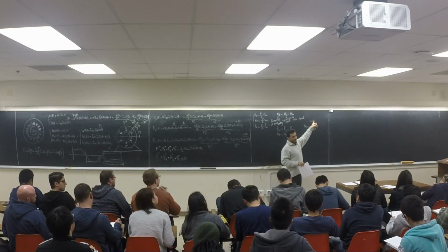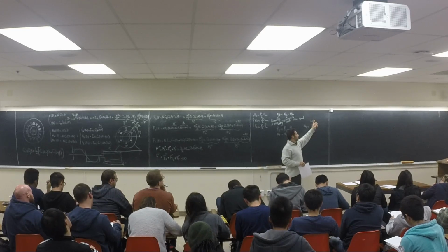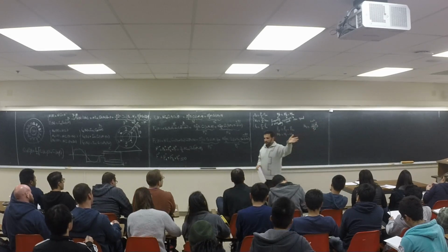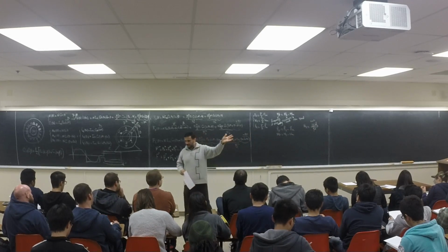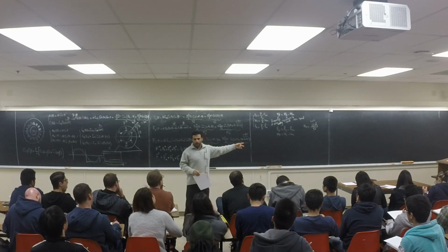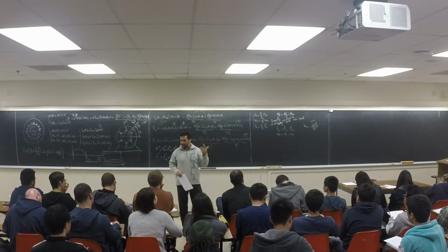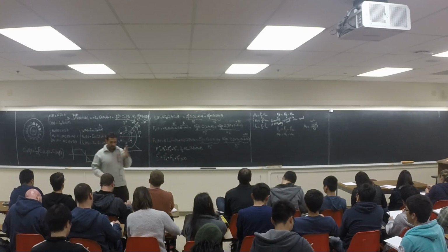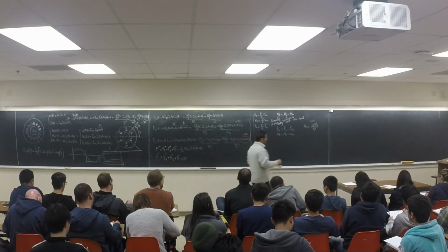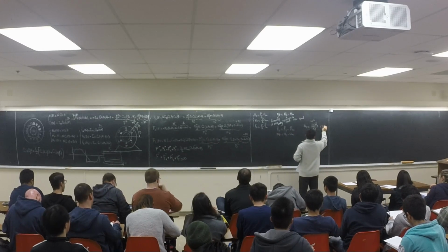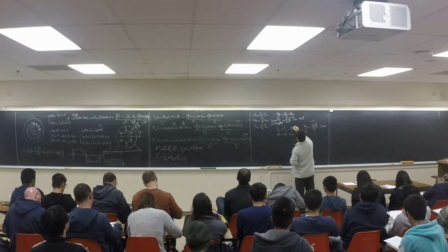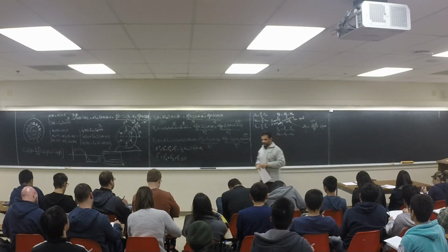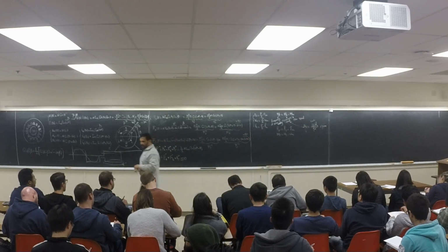Basically 60 is coming from the RPM. You want it per minute, right? Every minute is 60 seconds, right? 2 Fs over P is the RPS. RPS times 60 is going to be RPM, right? This one is RPM. Keep in mind, the unit for this one is the RPM. They call this one synchronous speed. I put it here already.